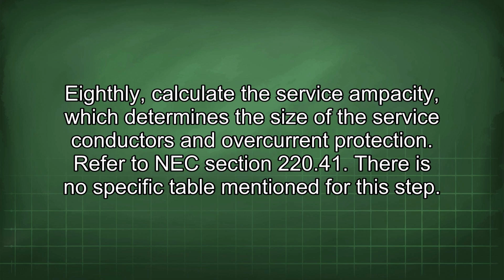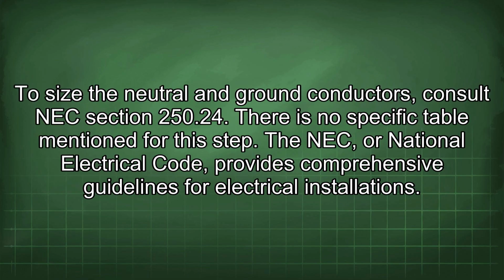Eighthly, calculate the service ampacity, which determines the size of the service conductors and overcurrent protection. Refer to NEC Section 220.41. There is no specific table mentioned for this step. To size the neutral and ground conductors, consult NEC Section 250.24. There is no specific table mentioned for this step.